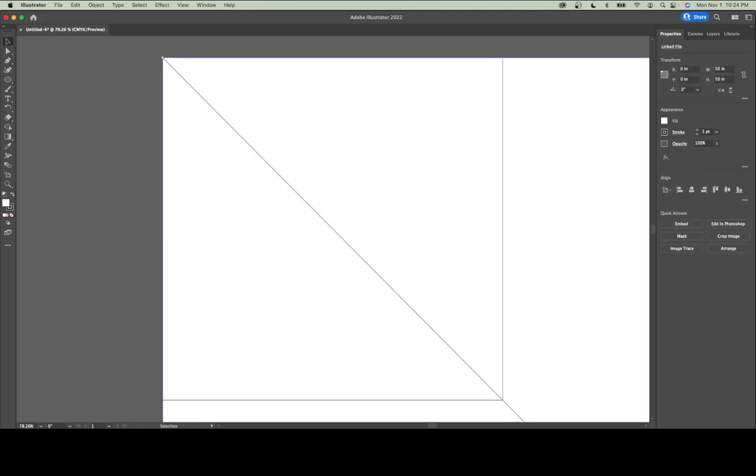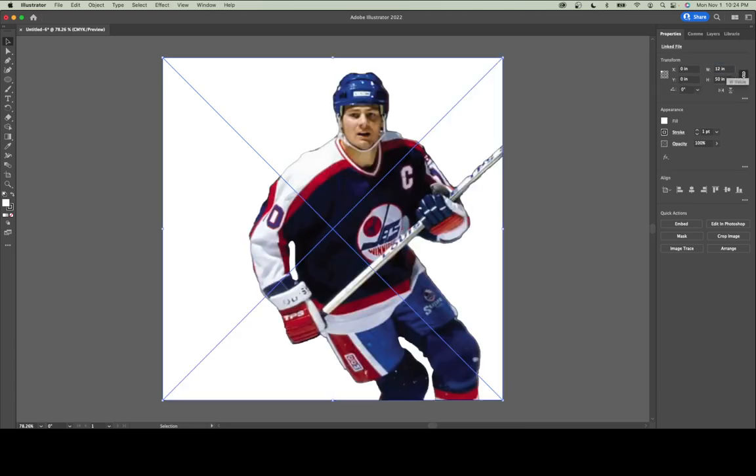And again, if this doesn't proportionally fit, just make sure you go to the Properties menu on the right-hand side. Choose the restrictions to keep the proportions proportionate and choose one of those measurements, make it 12 inches, and your document should fit. If it isn't visible, make sure you select that top left corner for your reference point and set your X and Y values to 0.